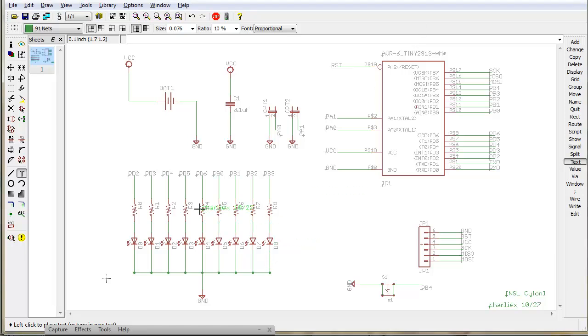One thing we haven't done actually, when I'm thinking about it, is assign values to the resistors. So what I'm going to do is, first of all, type the command correctly, and those resistors are 16 ohms. So I'm going to put 16 ohm, I'm going to put 16 ohm, and I'm going to click on each of these, and you'll see the name appearing as I click them. LEDs we don't really care about, so let's just do a quick triple check. Switch doesn't have a value, JP1 does not have a value, the IC doesn't, jumpers don't, capacitor we already did, battery we could put a value on it but we're not going to, so it's just really the 16 ohms, and that's for the particular color of LED that we're using.